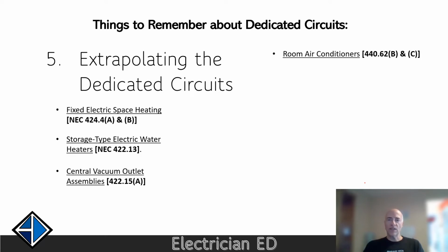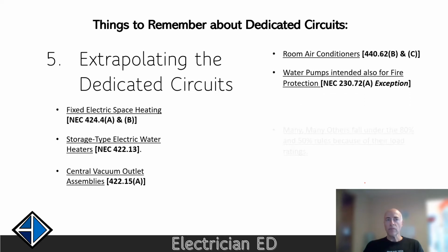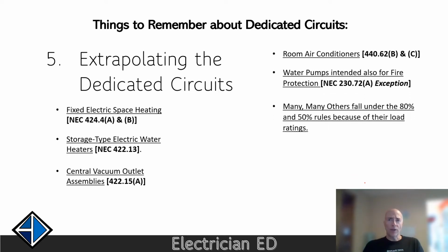Fixed ACs tend to require more than 10 amps. Some in-wall units are going to need even more than that, like at least 20 amps or more. So often they end up getting a 30 amp receptacle. Manufacturers also tend to call for dedicated circuits.